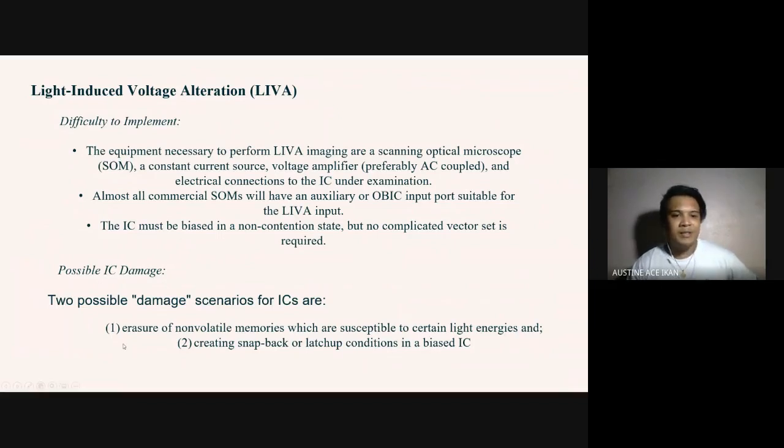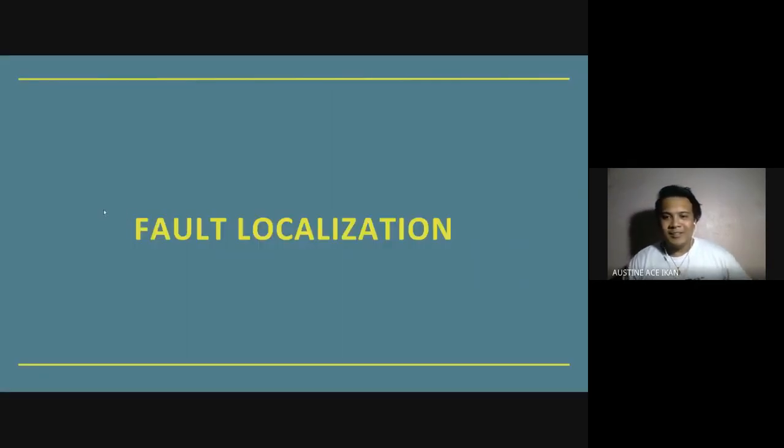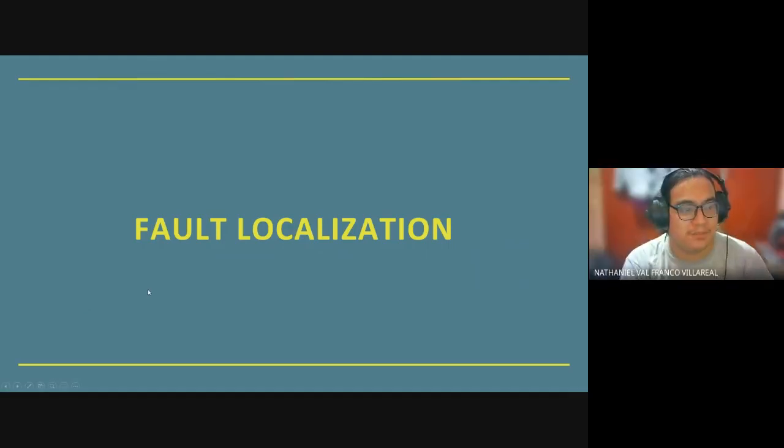As for possible IC damage, there is no physical damage in SOM, but there are two possible damage scenarios for ICs. Number one is erasure of non-volatile memories, which are susceptible to certain light energies, and number two is creating a snapback or latch-up condition in a biased IC, like in OBIC. So thank you for that report.